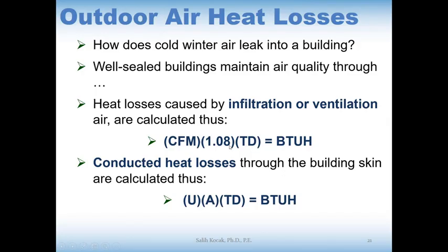1.08 is 1.08, it is not changing. And the infiltration rate was 4,000 and the ventilation rate was 6,000. So I have to use the larger one of them. And 6,000 is larger than 4,000, so I'm going to use the 6,000 here as the CFM value.